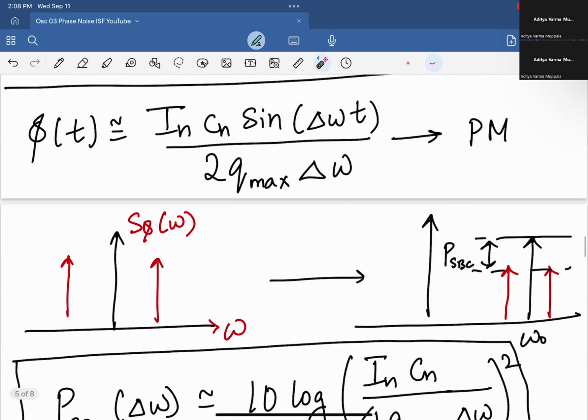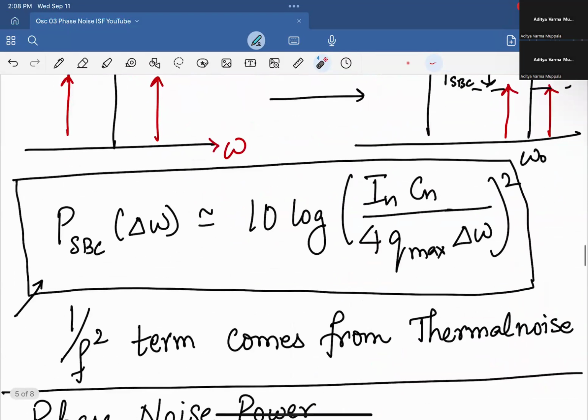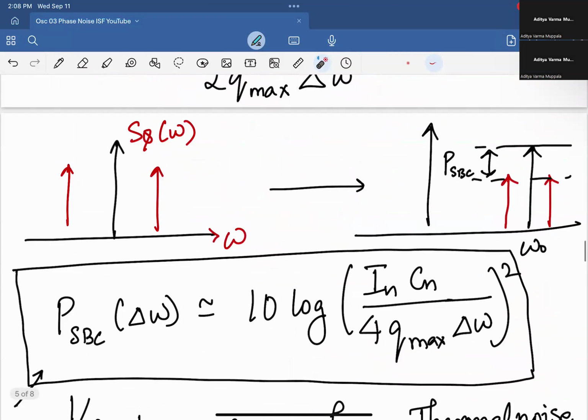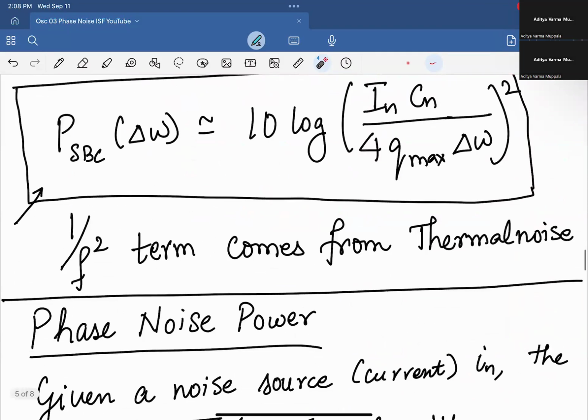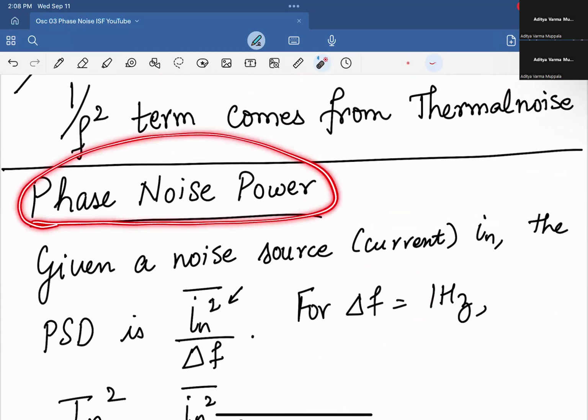Okay, that's a lot of words, I guess, but eventually we showed that because the modulation index is low, we can find what the sideband power is for these modulated tones. And we use that sideband power to form a quantitative model of the phase noise.